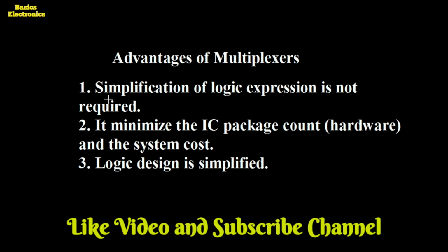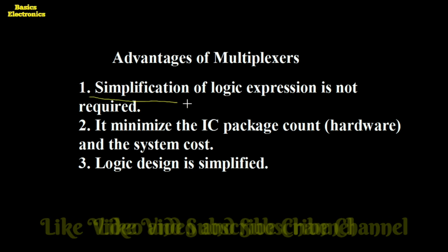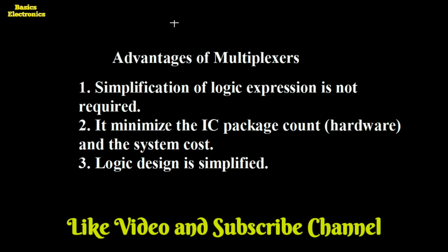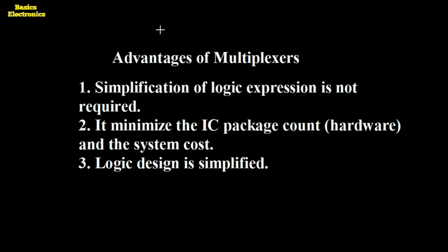The first advantage is that simplification of the logic expression is not required. It means that when we use the multiplexer to implement any logic circuit, we do not need to simplify the logic expression by using the laws of Boolean algebra. For example, suppose we have the equation (a bar b plus a b bar) multiplied by (a bar b plus a b bar) multiplied by c.